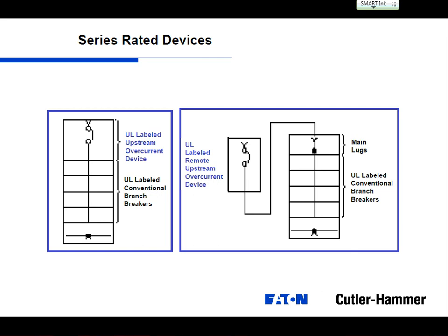But the advantage of having it upstream is you can completely physically isolate that piece of equipment from electricity. So you can take the whole panel. Yep, versus you can't do that if you have the main inside the panel. Absolutely. That's a major advantage of having the circuit breaker outside the panel too. And Chad made a good point.